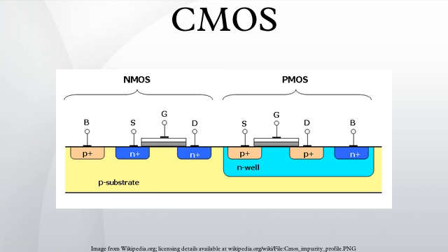Technical details: CMOS refers to both a particular style of digital circuitry design and the family of processes used to implement that circuitry on integrated circuits. CMOS circuitry dissipates less power than logic families with resistive loads. Since this advantage has increased and grown more important, CMOS processes and variants have come to dominate, thus the vast majority of modern integrated circuit manufacturing is on CMOS processes. As of 2010, CPUs with the best performance per watt each year have been CMOS static logic since 1976.